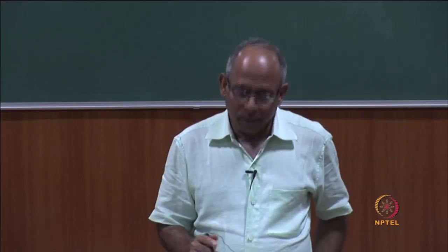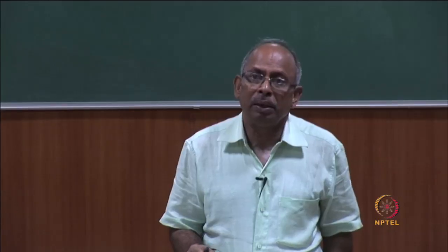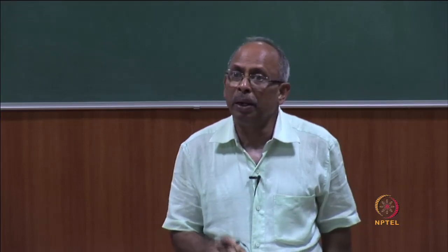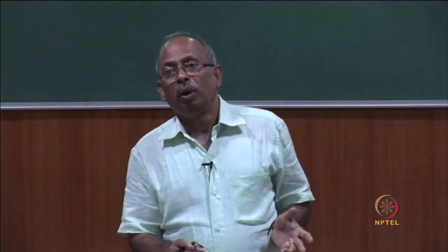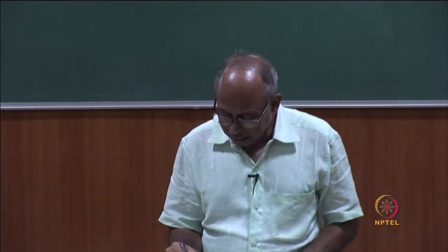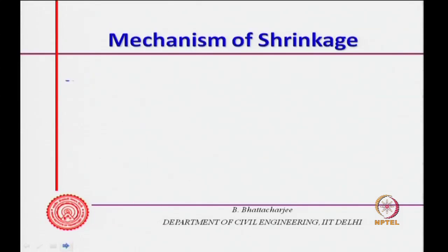And because of these phenomena, if you add water back, the pressure will not be the same as what it was earlier. Similarly, the surface energy restoration, if you do by adding water back, may not be exactly the same as before. So, putting all this together, the shrinkage is not fully reversible, and this is possibly because of breaking of the bond, and possibly formation of additional bonds. So, that is what we understand about shrinkage, its mechanism sort of.